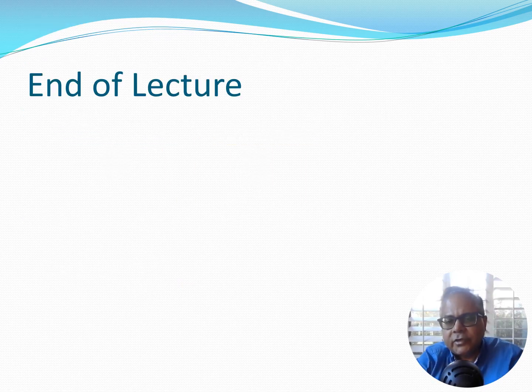So today's lecture introduced you to a very important number, that's the Reynolds number. It's like the brother of Mach number as far as aerodynamics is concerned. Whereas Mach number deals with compressibility, Reynolds number deals with viscosity and viscous flow. And we also saw that at different flight regimes or at different scales and speeds, the Reynolds number for different types of flight vehicles are different, and so the importance of the viscous effects becomes more as the Reynolds number becomes less. So for example, if you are dealing with micro air vehicles or small vehicles, the effect of viscosity is going to be more.